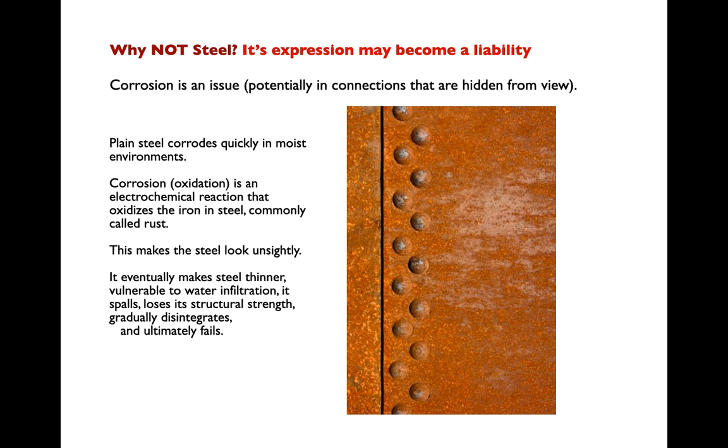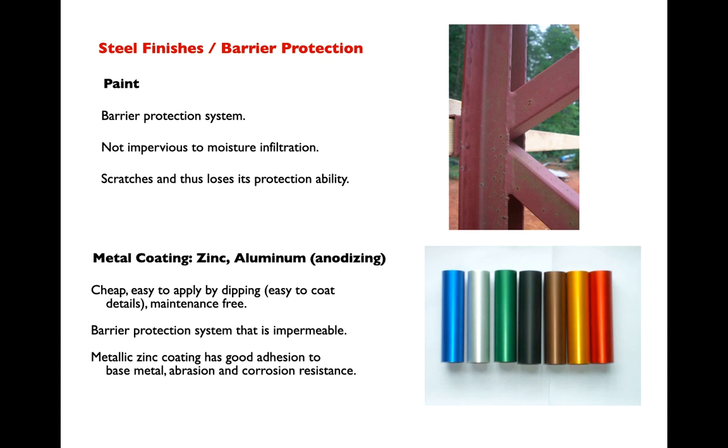There are alloys, for instance, Corten, that rely on oxidation to protect steel beneath. These are of varying popularity, right? The general public does not like to see a rusting steel building, typically. And we guard against this in a couple of ways. We can either use alloys to guard against corrosion. So stainless steel uses additional nickel to create a very, very thin molecular layer of protection that prevents oxygen from reaching into the inner steel core.